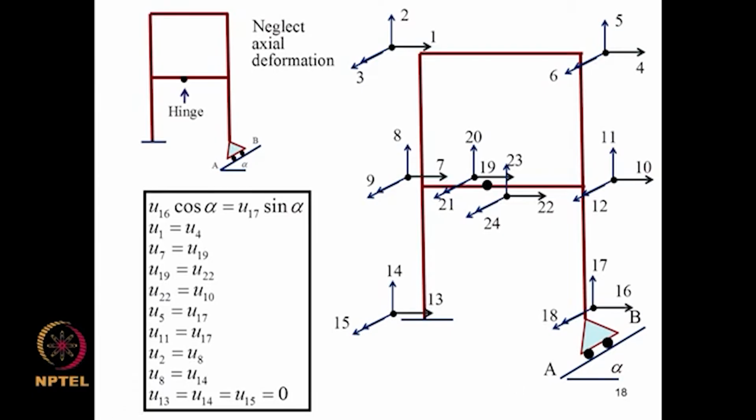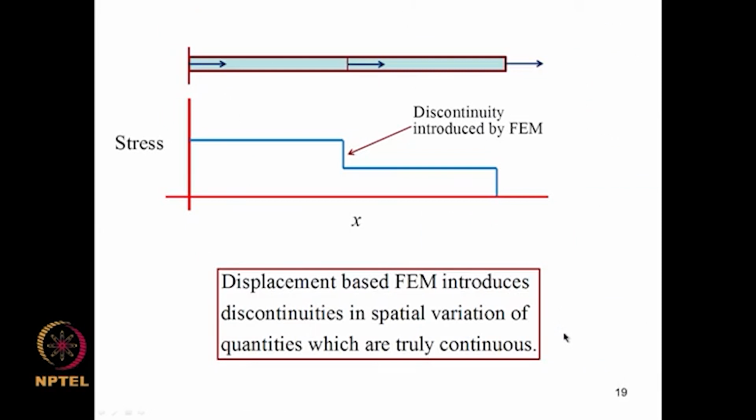We started by studying planar frames and modeled elements as Euler-Bernoulli beams. We considered questions about how to deal with a hinge and a roller on an inclined support, etc. That is, how to set up suitable constraint equations in terms of degrees of freedom to correctly capture the presence of a hinge or an inclined roller, and so on and so forth.